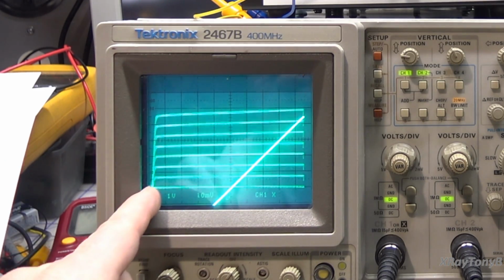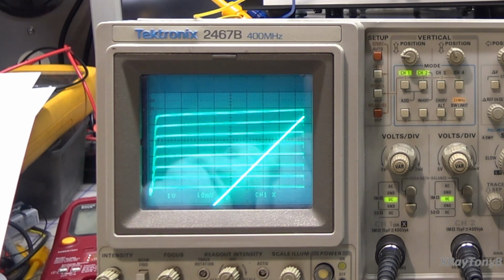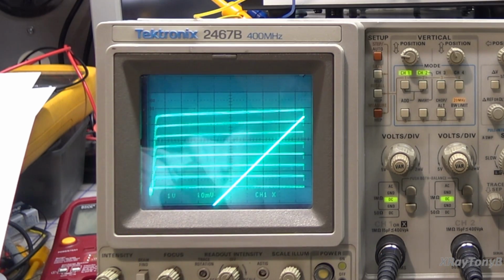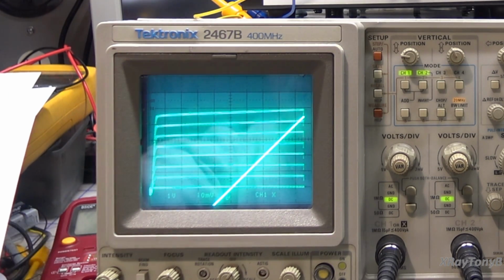Here's 0 volts down here in the corner. If you drew it clear off of the scale and drew them all together, they would converge at 0 volts at a certain point. And that convergence there, or 0 amps, I'm sorry, 0 current, at the point at which all of those converge at 0 current, that negative voltage, that's called the early voltage.